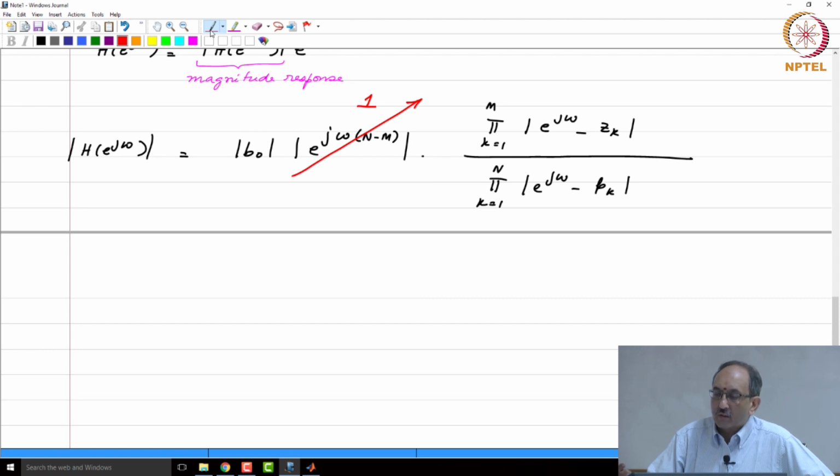No, I think when you are saying it approximates a straight line, you are thinking of the Bode plot, and that is log. Here I am talking about the x axis frequency being still linear, but the y axis being log magnitude, and typically it will be 20 log 10 or 10 log 10 magnitude squared. But given that 0 to 1 is not a large range, why is it that you still want to plot this on a log scale?